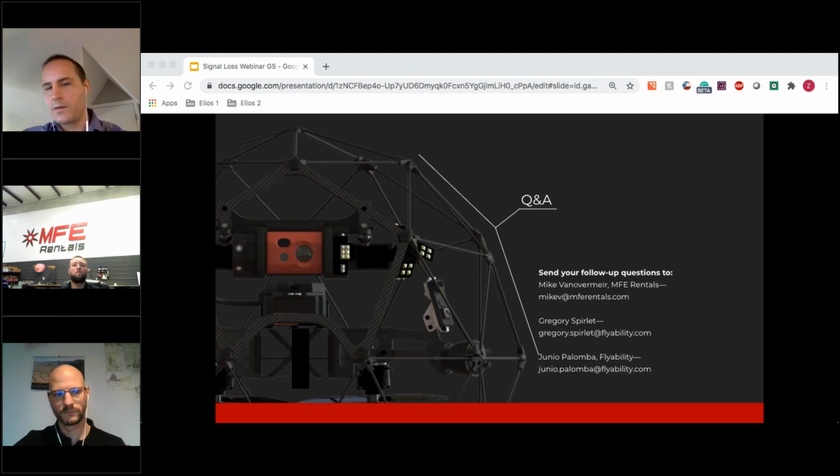Another question, Greg, I'll go back to you. How would you assess the reflectivity of a PE lined pipeline? Depends on the thickness of the lining. PE would be slightly absorbing or transparent. So if there's steel behind the PE and it's not too thick, I would say it still counts as reflective, but you probably wouldn't expect the same range as in a bare steel environment.